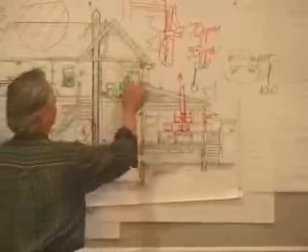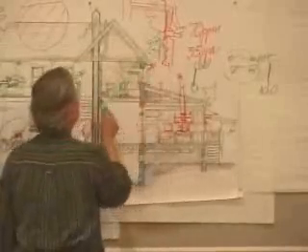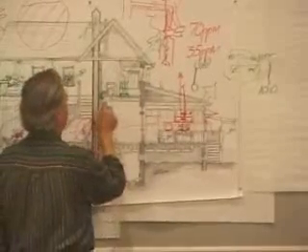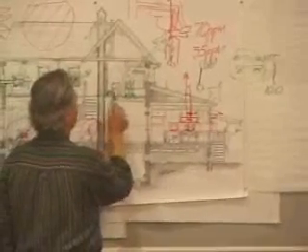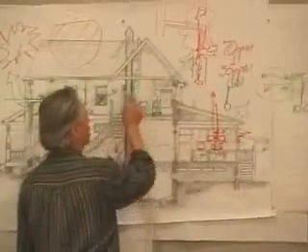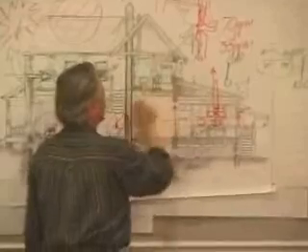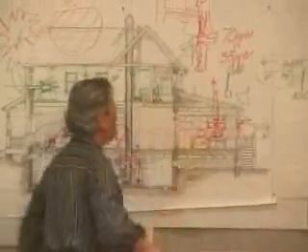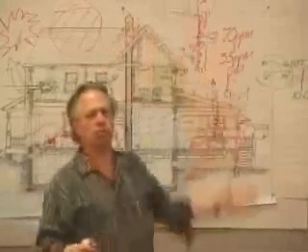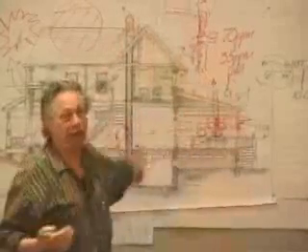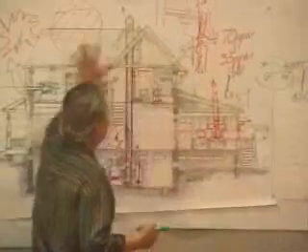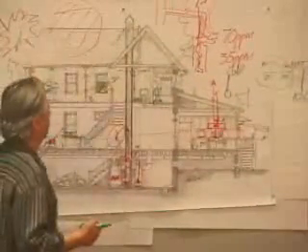And you definitely don't want a fan to blow air out without making sure there's some way for air to get in, and sometimes that's just cutting the bottom of the door off so you got some air coming in this way. This worked better when they used to have a transom up there because then the breeze wasn't past you, it was above you. So it's better to get the air over the doors because you don't want a draft on you in the bathroom for the most part. So the way that the air moves through this house becomes critical.